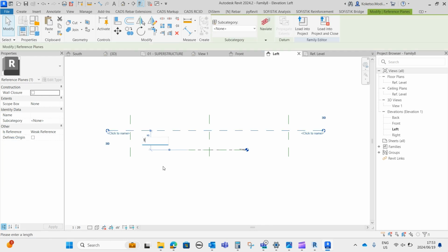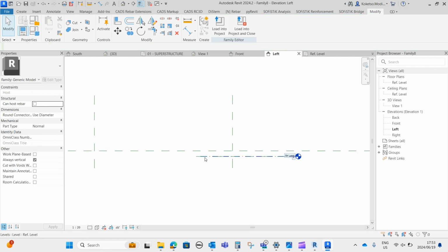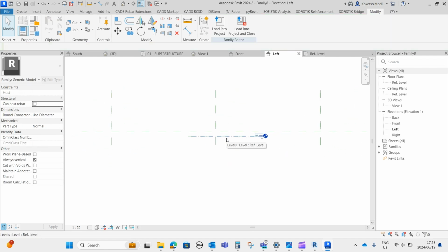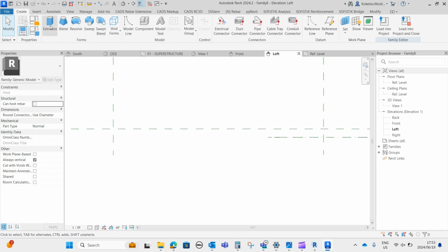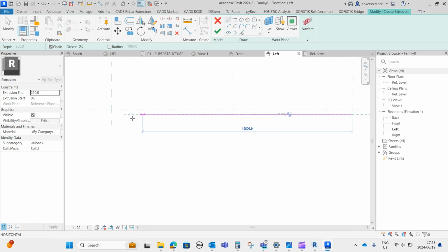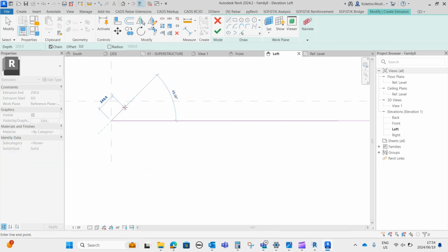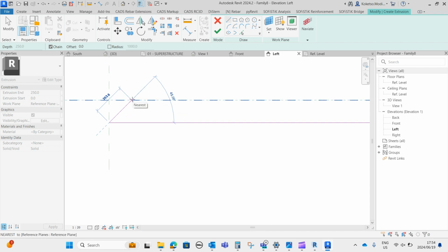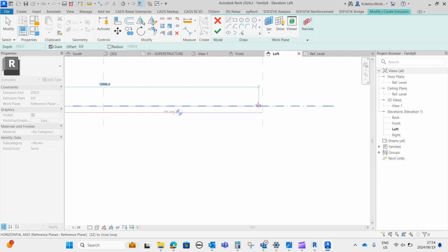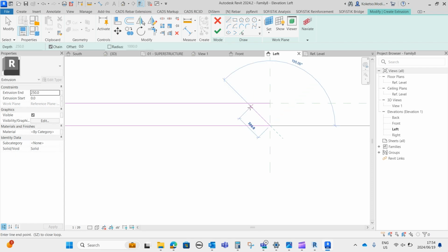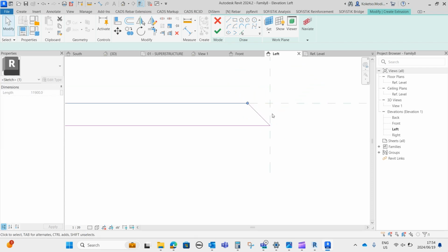You're gonna place another one on top like this. So this one you're gonna offset it by, I think we can make it 100. Our ballast we can make it, let's see, 250 millimeters. I think that's fine. So for our ballast, we can say create and say extrusion. So we're gonna place a horizontal line at 2,400 millimeters, and then a diagonal line at 45 degrees like this, and also on this side you can place it at 135, and then you can adjust this like this.